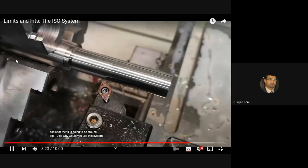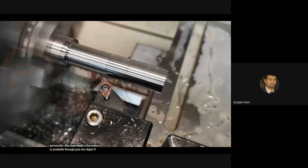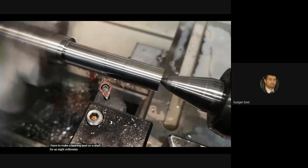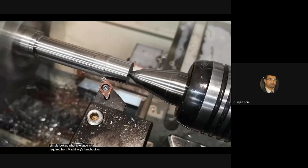So why would you use this system? Personally, I like how much information is available through just two digits. If I have to make a bearing seat on a shaft for an 8mm bearing, I can simply look up what tolerance is required from Machinery's Handbook or something similar.